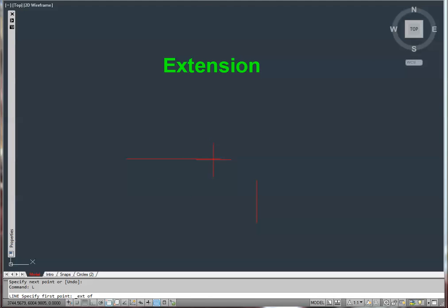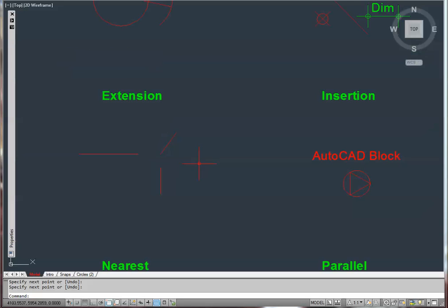Now just hover over the end point, and it'll pick up a little green plus there, and again hover, and as I move up you'll see these tracking lines appear. When I get to where they intersect it'll show the extension tooltip saying the angle of 0 and the extension angle of 90. So click on there and there we have it. We've snapped to the extension of the two lines.